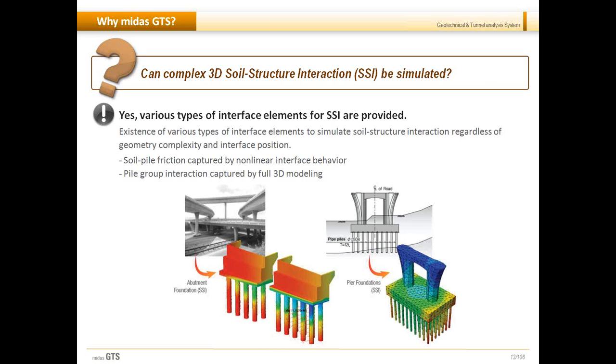GTS is also very powerful to analyze the soil structure interaction between the pile structures and the soil. We have special elements which model the nonlinear behavior between the pile and the soil and capture the friction of this behavior. And all that is modeled in 3D, of course.